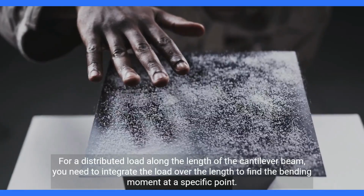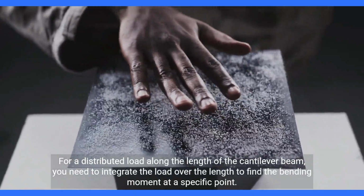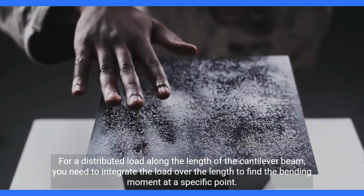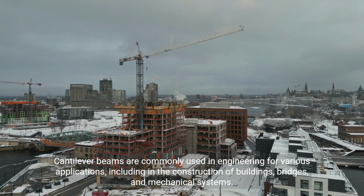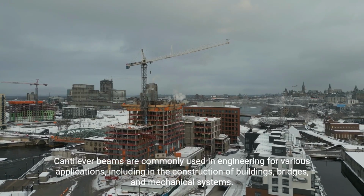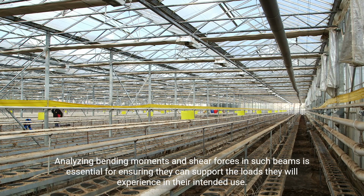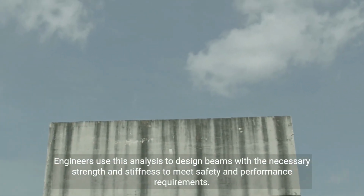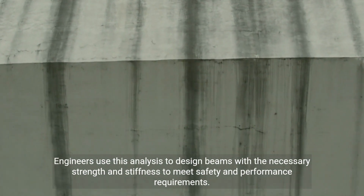For a distributed load along the length of the cantilever beam, you need to integrate the load over the length to find the bending moment at a specific point. Cantilever beams are commonly used in engineering for various applications, including in the construction of buildings, bridges, and mechanical systems. Analyzing bending moments and shear forces in such beams is essential for ensuring they can support the loads they will experience in their intended use. Engineers use this analysis to design beams with the necessary strength and stiffness to meet safety and performance requirements.